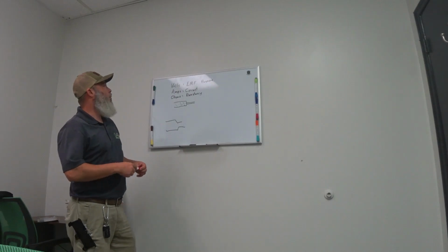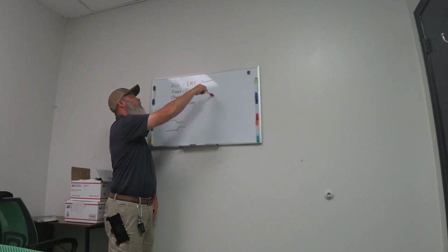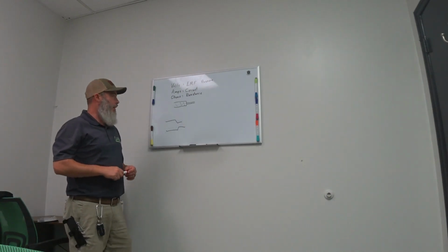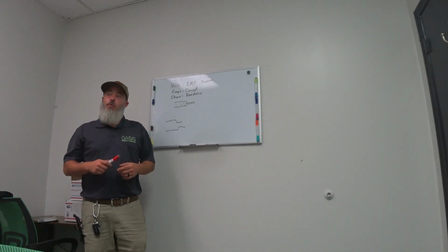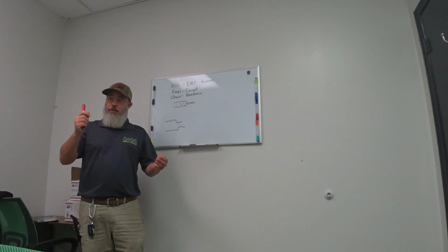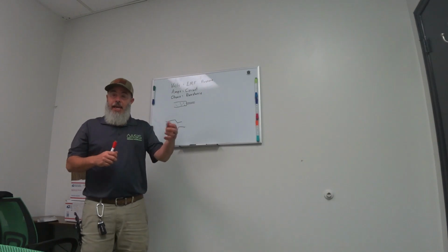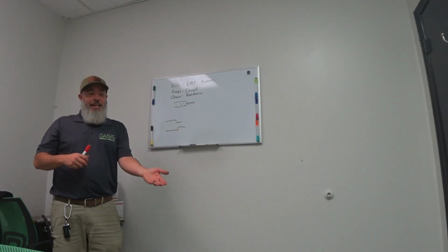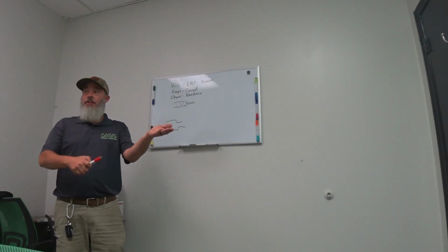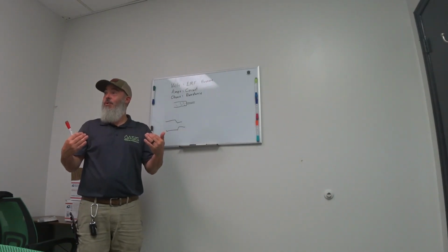So we use resistance to troubleshoot with a lot, because you've got a float switch. When it starts out in the fill cycle, the water valve energizes and the sump starts filling up with water. There's a float that is coming up as that sump fills up. When the sump's full, the float tells the board the sump's full, so boom, it shuts the water valve off.